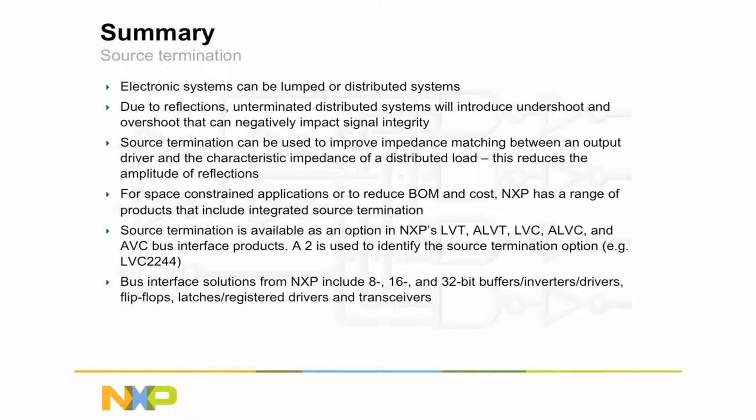Source termination is an application-driven feature developed to replace resistors used in impedance matching of distributed systems. NXP offers a range of 8-bit, 16-bit, and 32-bit functions with source termination. These reduce bill of material and placement cost, as well as reducing the footprint of an application.